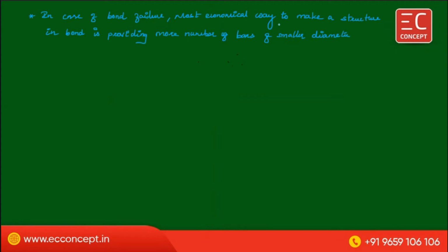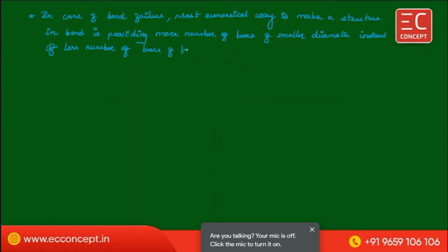How can we increase the bond stress? Bond stress can be increased by providing more number of less diameter of bar. That is smaller diameter instead of less number of bars of larger diameter. So this is the answer. I hope you understood.